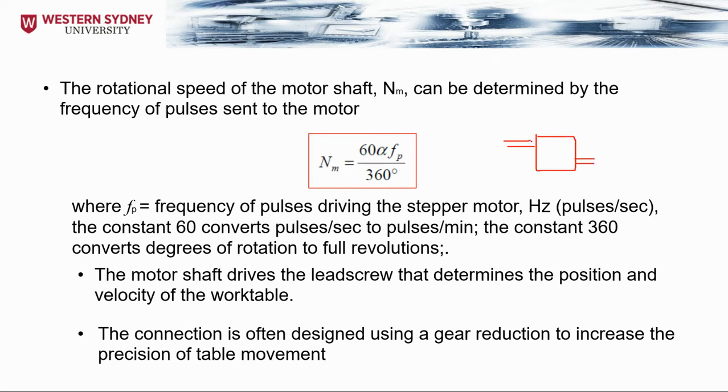We're going to have two gears. The first gear here is quite small, for the bad drawing, and the other one is large. The large gear provides a lower RPM value for the output shaft. So we have the N for the motor here and the N for the screw on the other side.